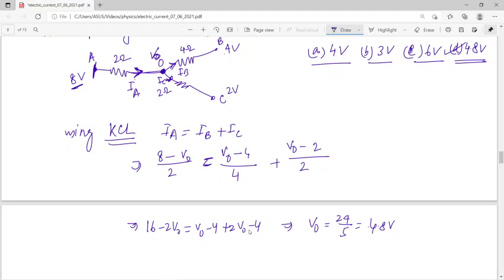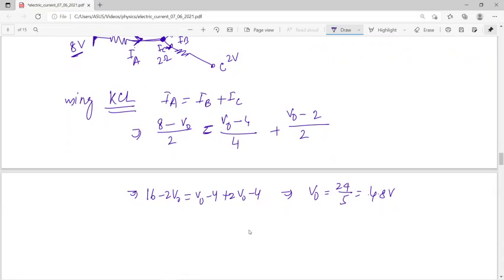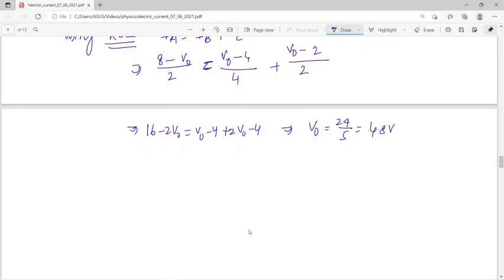So just remember, if you can solve the problem by using KCL, it always requires fewer equations compared to solving it by using KVL. There is a method based on KCL, which is called nodal analysis. That is nothing but nodal analysis. And what is nodal analysis?